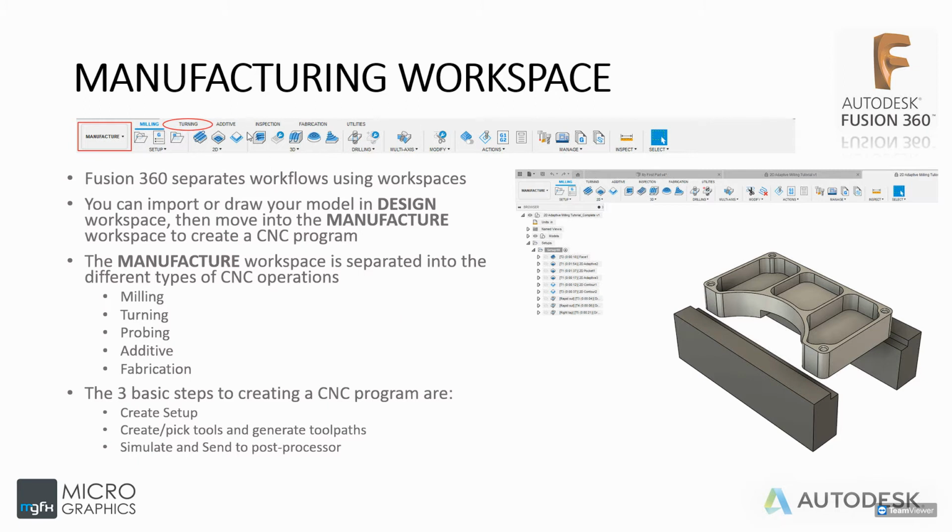But the gist of it is that 2D will create toolpaths for each step down. So it'll basically do everything on one level, step down in the Z direction, and do everything on the next level, and so on and so forth. Whereas 3D can go from one Z level to the next, to another Z level, to a next, and it doesn't necessarily rely on stepping down and then clearing everything at that level. So that's the difference between 2D and 3D.